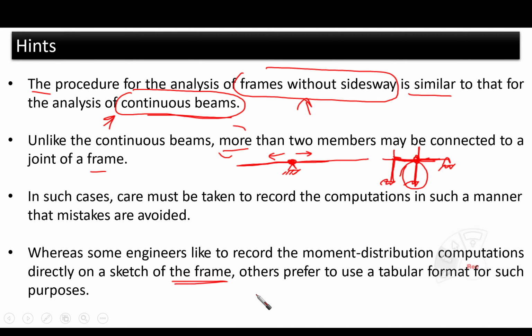So they like to have the frame itself, and then they put the moment distribution and the fixed end moments and the carryovers on these branches of the frame elements itself, or the frame members itself. This is okay, and it is based on the practice of the engineer itself, but again it is based upon your preference, which type of procedure you like and representation method you like.